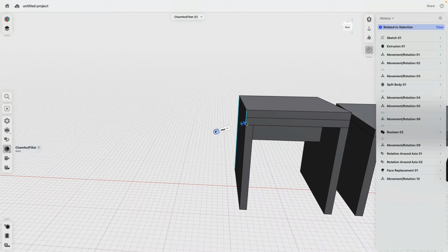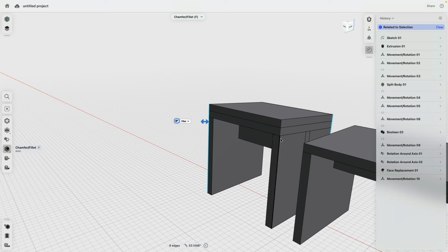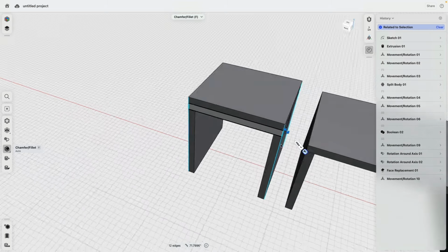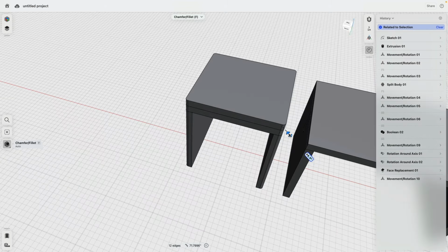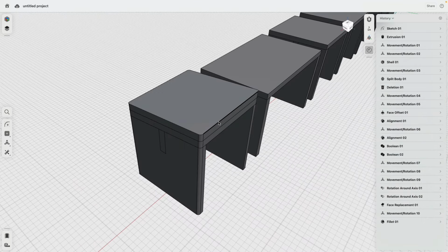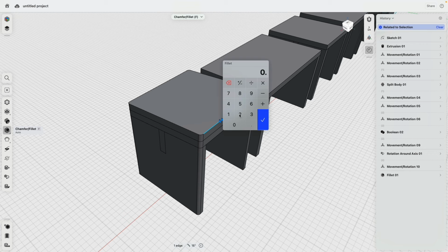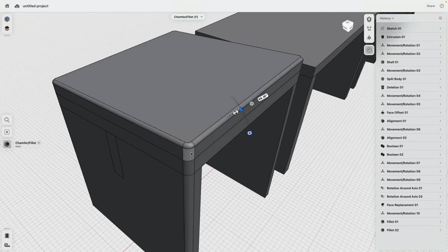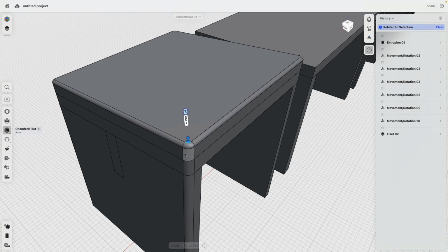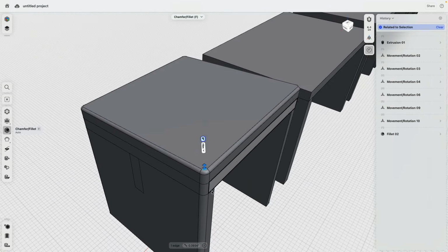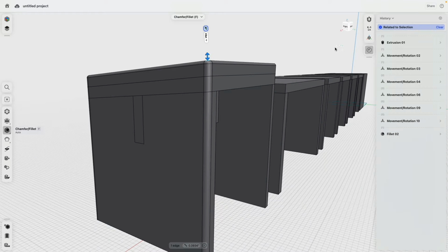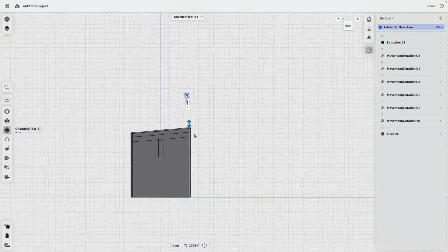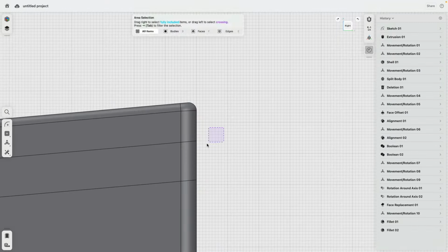We're going to select these vertical edges, and then we will round them a little bit. Well, let's say 1/2 inch. That's okay. Then we can select this one, type in 1/4 inch. The second fillet should always be smaller than the first fillet or rounding, so you get these nice, beautiful rounded corners there.